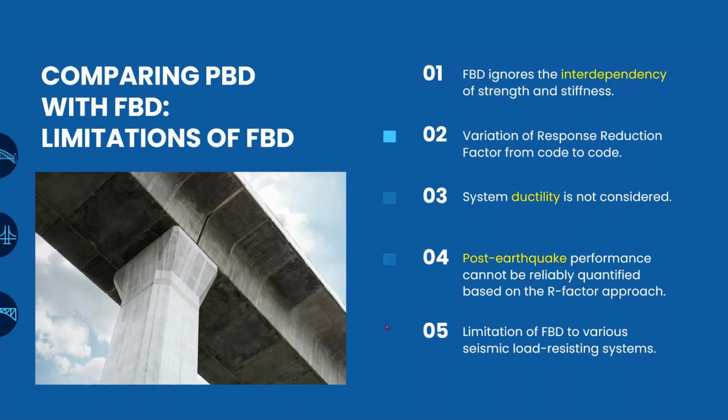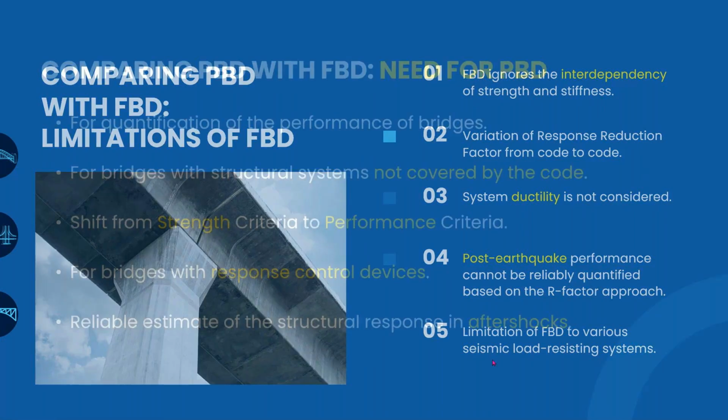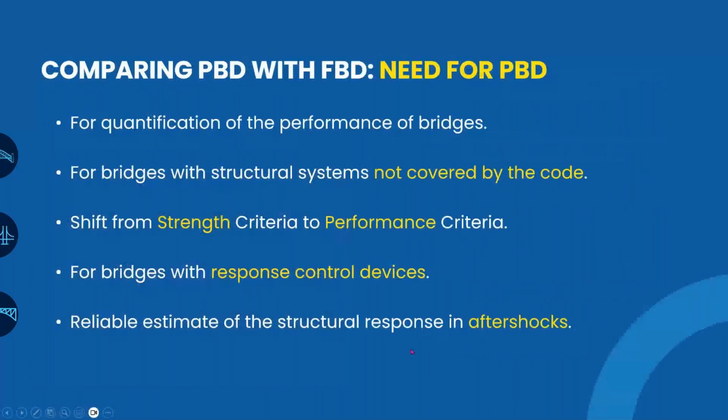And hence, due to these limitations, performance-based design comes into the picture. Under performance-based design, the quantification of the performance of the bridge is possible. All the structural systems which are not covered in the code can be easily covered by performance-based design.